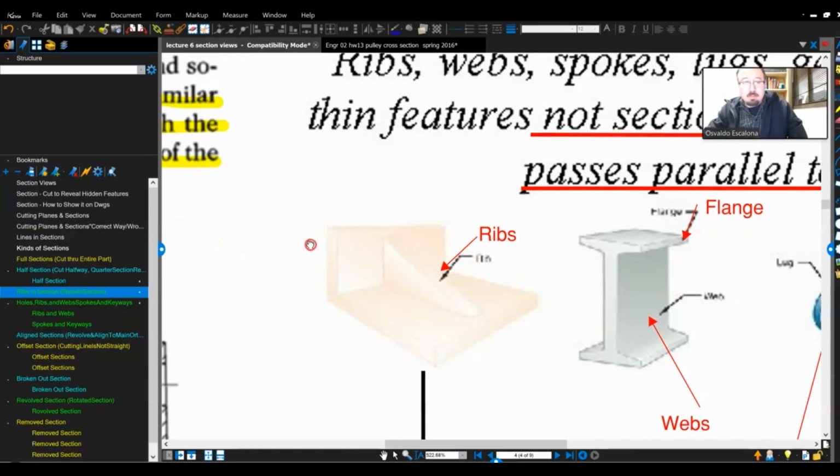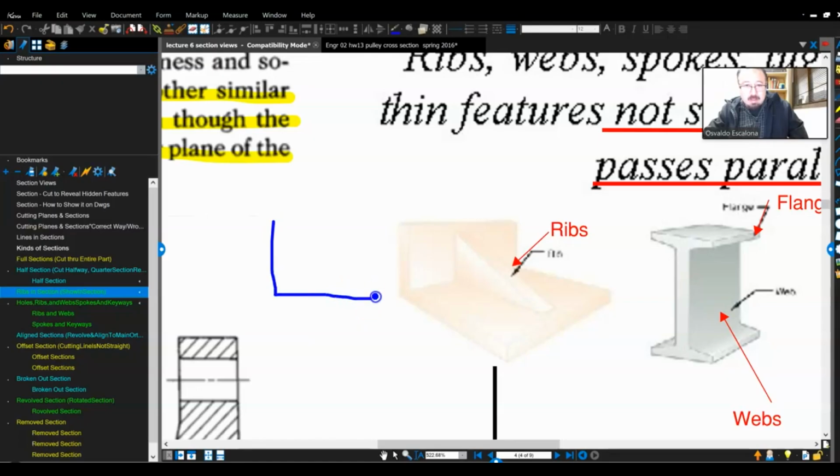They are placed for parts that look like an angle, or something that can deflect sideways, like this, right? Why do they deflect sideways? Maybe because there is a load. It makes it flip. So to prevent this flippiness, sometimes they put in a gusset. A gusset is just a piece of metal, a piece of material. Usually you call them gussets for metal assemblies.